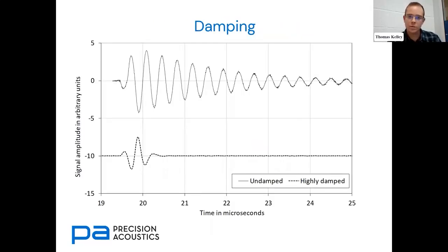So that leads us on to damping within a transducer. Bandwidth has implications for pulse shape as well as frequency content. We've got a slide here which has examples of the impulse response of two different transducers. The top trace, or the A scan if you prefer, is a good example of the impulse response of a narrowband transducer. It's a relatively high amplitude, and it lasts for many cycles.